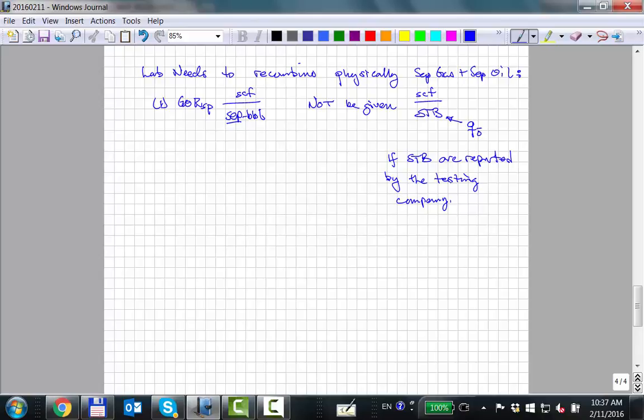And over a 48-hour test, it's a lot of rows of data. Maybe it's every 5 minutes, I don't know. And it says oil rate barrels per day. Then you don't know if it's separator barrels per day or stock tank barrels per day. And the difference can be a factor of 0.7, so it makes a difference.